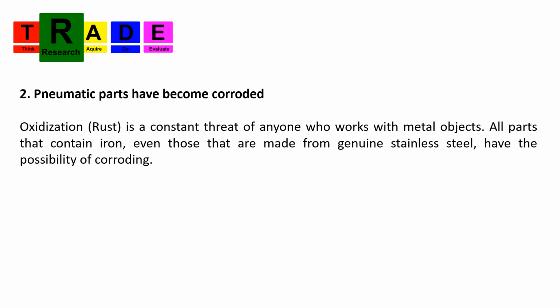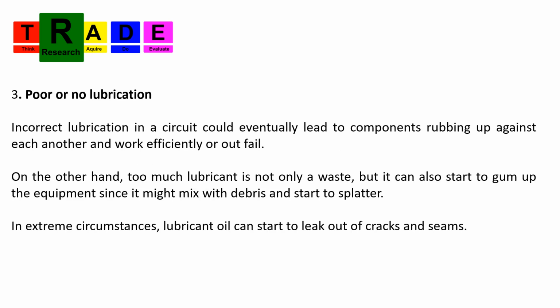Should I be using stainless steel components in my pneumatic circuit? Is the filter lubricator working correctly or being maintained correctly? Is the lubricator working? Is it injecting a sufficient amount of lubricant into the system?